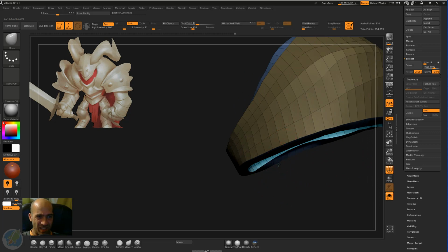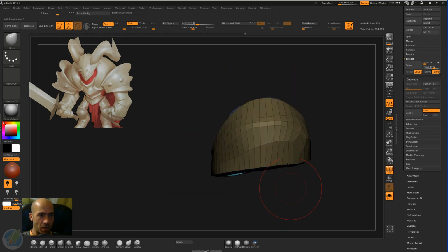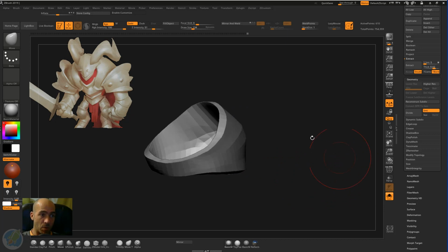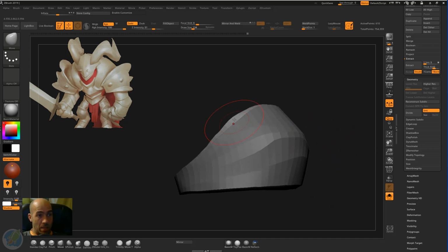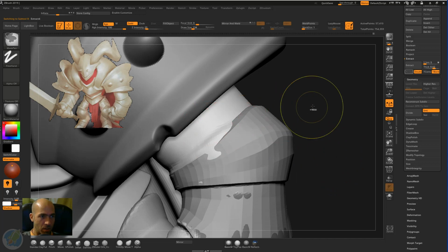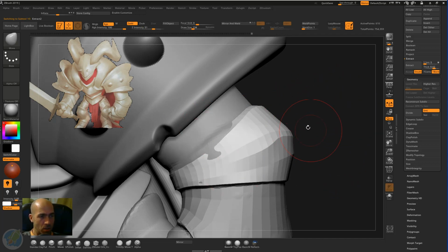You will have a mesh that you will not be able to control easily like we are controlling it here, because low polys are much easier to control than high polys. So that's a big tip, and hopefully you will remember. When we have this, we have it and it's cool. Don't Dynamesh it ever. So now I will control drag to disable the mask.